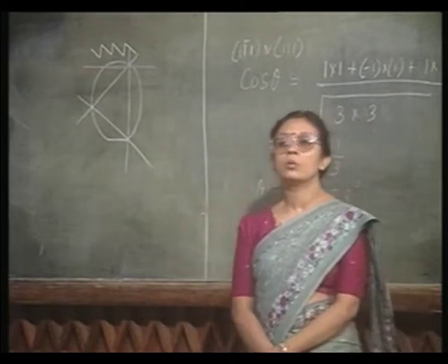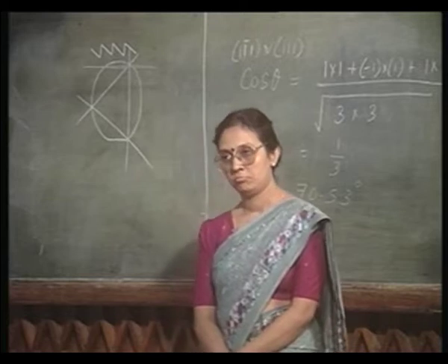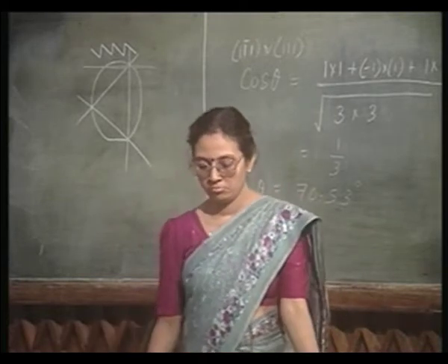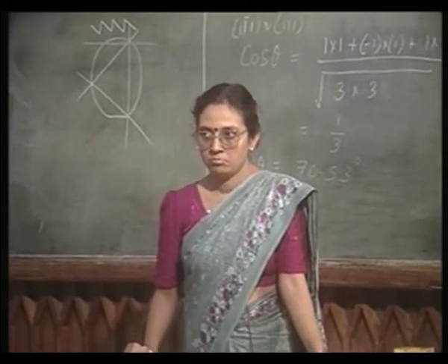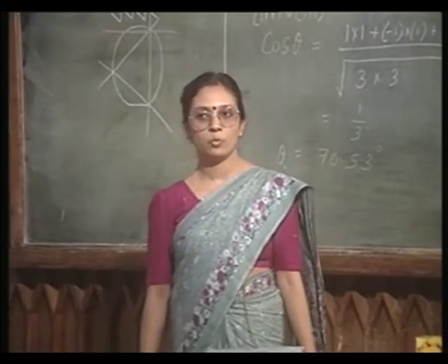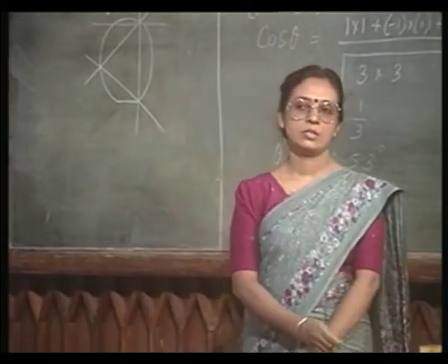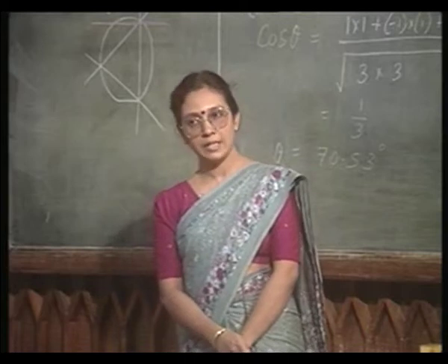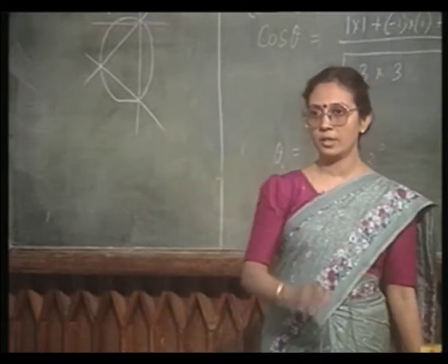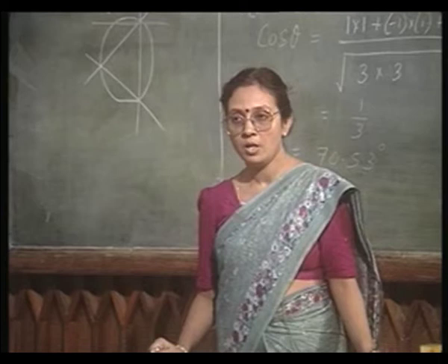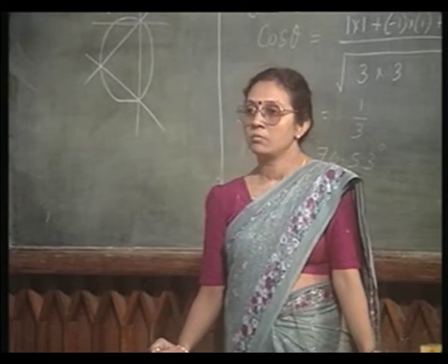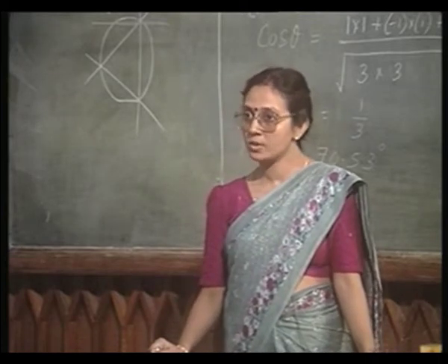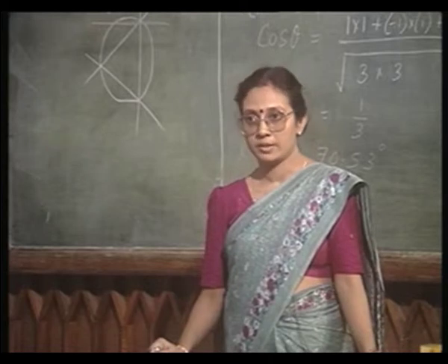If I have 110 silicon, it is going to be very interesting. Again you see the first point is common, when I am cleaving it is going to be 111 planes, cleavage plane is going to be 111 planes.